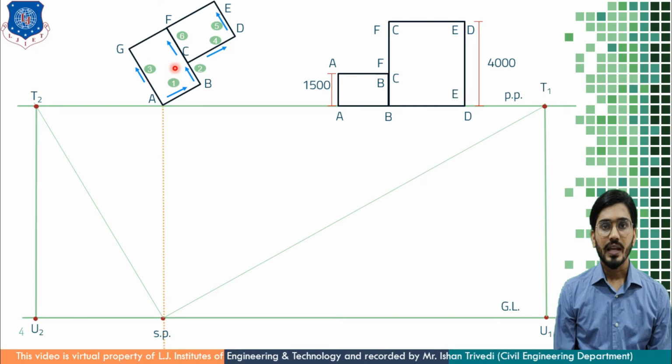C to F. As I have told you, B, C and F are on the same line, and as BC is on the left hand side, C to F is also in the left hand direction. Then F to E, again it is on the right hand side, and G to F. As this drawing is a little bit slanted, make sure your drawing is not going off the sketchbook. Before you mark anything, just put up the points and later on draw all these lines.